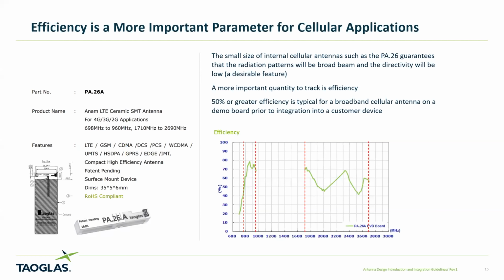Well, yeah, there's a lot of challenges. What has always been a challenge since LTE came along was the need to integrate two antennas in that small volume. Another challenge, which was hitting in 2008, 9, 10, and has kind of stabilized, is the smartphone became extremely thin, again putting stress on the antenna. So it's very difficult to get any antenna height above a ground plane. We're always looking for separation between an antenna and ground plane to provide more efficient radiation. So that is typically a problem. And the inability of getting the antenna away from a battery.